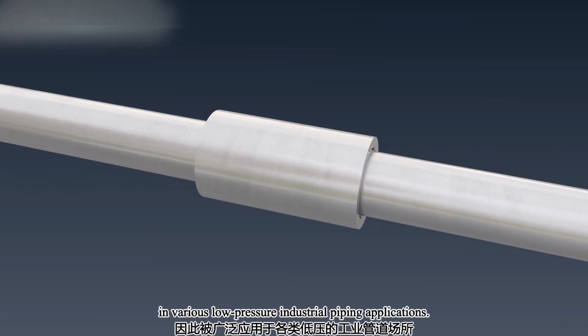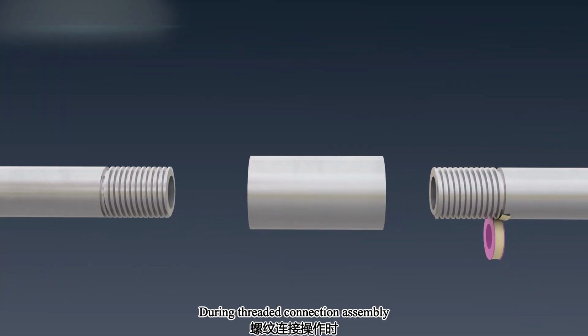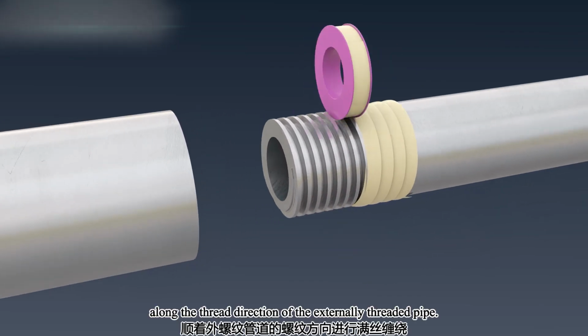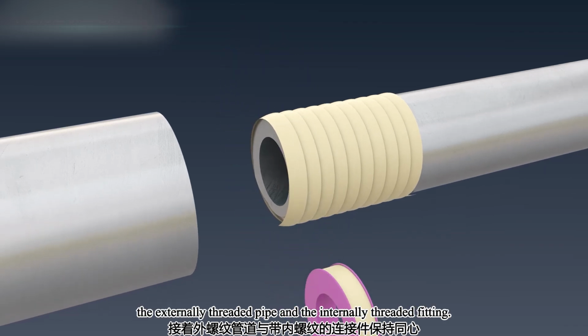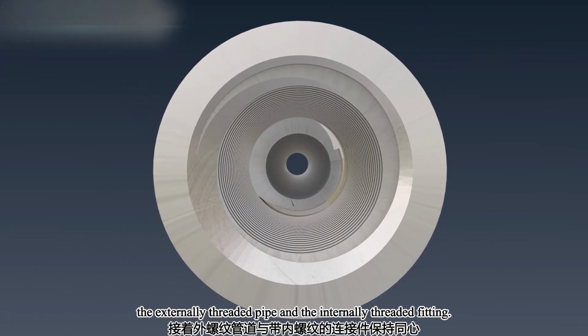low-pressure industrial piping applications. During threaded connection assembly, first wrap the sealing tape fully along the thread direction of the externally threaded pipe. Then maintain concentric alignment between the externally threaded pipe and the internally threaded fitting.